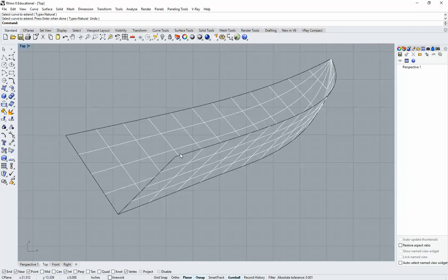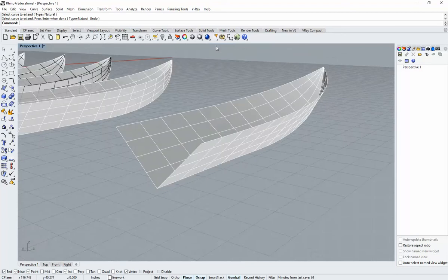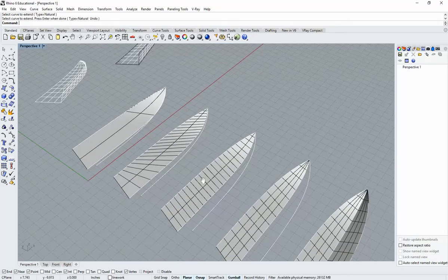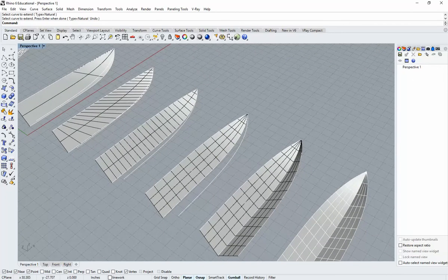Okay, and that's just a little Make2D trick that you may or may not be aware of, that you can extract line work, put it over your surfaces, and Make2D the whole thing together in order to produce drawings like this. And here you can really read the curvature very clearly, and you can also read that it's made of these, in this case, very thin surfaces. Okay, so that's just a lightweight introduction into the relationship between curves, how you draw them, and what the output surfaces are, and why it's useful to work in such a way where you're conscious of that.